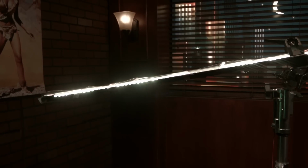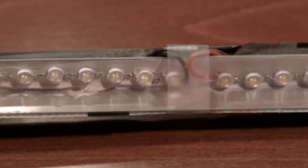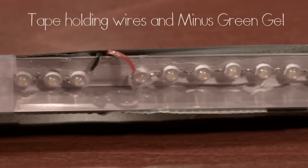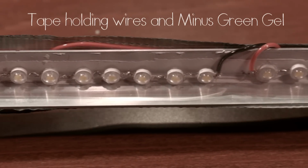But you can even build really far out there lights. I love the look of long strip softboxes, so I tried to build an even longer strip. I took a 5-foot angled aluminum and smeared heatsink glue down the entire edge, and then laid 15 sets of 8 warm white LEDs.